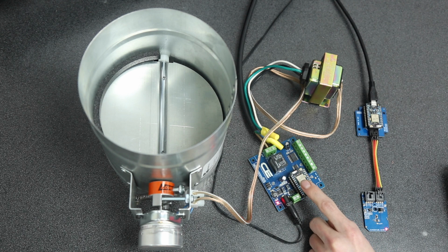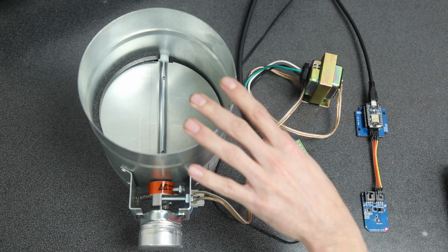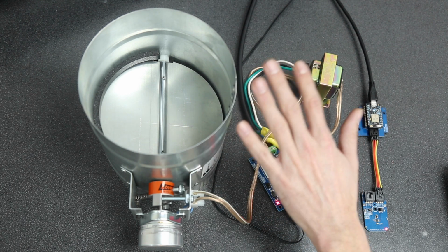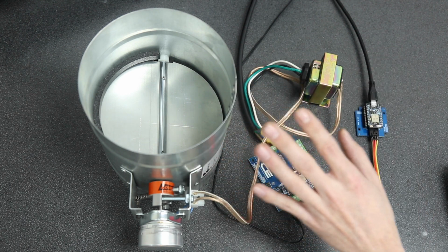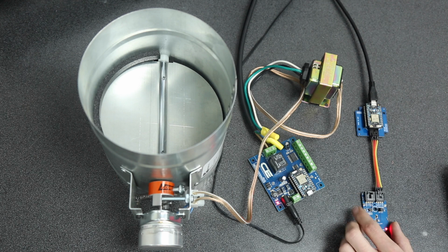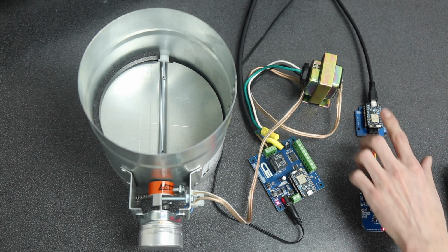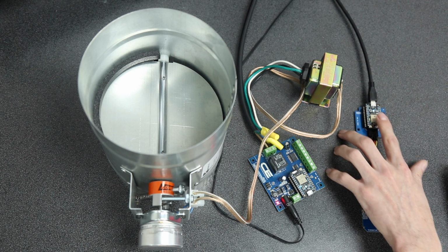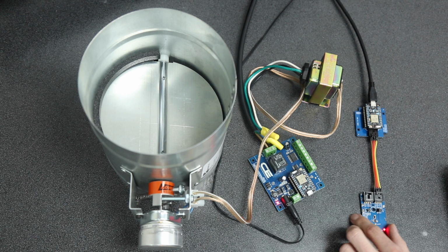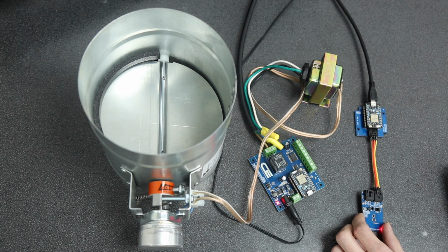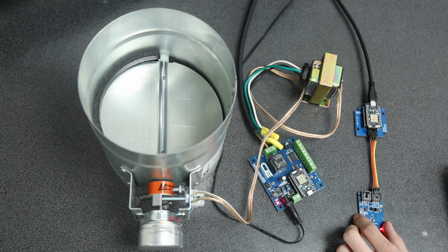And that relay is going to be controlled by this Particle Photon module. So this allows us, from the cloud, to be able to open and close this damper. So that's the first part of this application, basically controlling the damper open and closed. The second part is monitoring the temperature in the room that you're controlling. So for that, we have a Particle Photon module installed and an I2C shield connected to an MCP9803 temperature sensor. This is going to allow us to get temperature readings from the room and then control that damper accordingly.